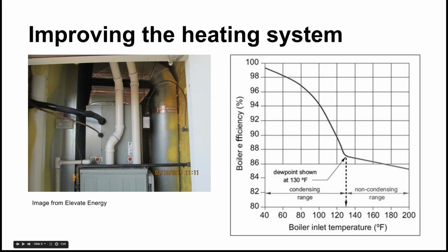So what we want to do instead of focusing on the combustion efficiency is look at the system efficiency, at maximizing heat delivery to the units. And one quick note here, you might notice that I'm not talking about cooling a lot, and that's because I live in Chicago. It's really cold most of the time, and cooling systems are not very common. Occasionally we'll see air conditioning units, just window units in the buildings, but there's not a lot you can do there, so I'm focusing mainly on the heating.